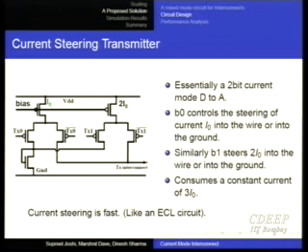So for the same, because I have biased this so that this comes to Vref, right? Choose the size such that it comes to Vref. So that means the drain is Vref here, drain is Vref here. So irrespective of which transistor is on, you see the same conditions always. Therefore the source voltage never has to change. Therefore even internally the voltage is dead steady. Even as you switch, the voltage is dead steady.